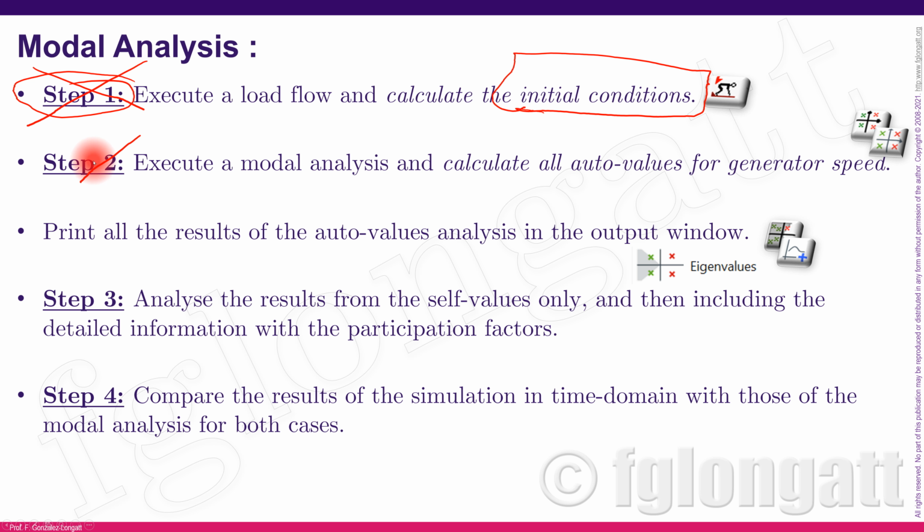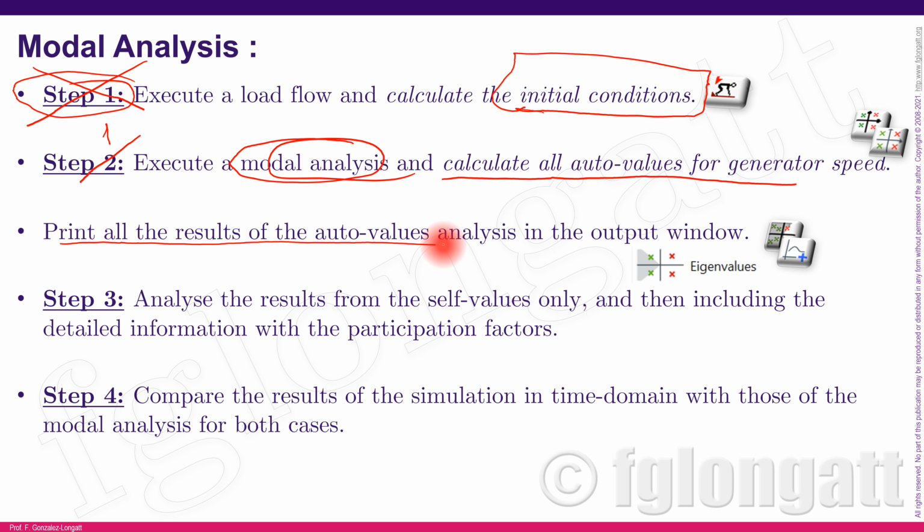If you are using the version 2021, you can go directly and calculate the eigenvalues using the modal analysis functionality inside PowerFactory. And then you can print out the results using the eigenvalues analysis. You can do that using the output window, for instance.